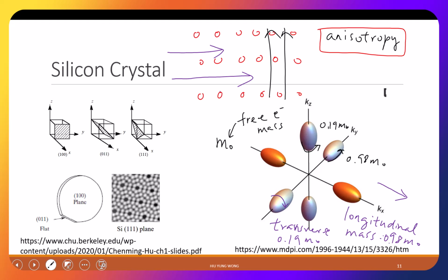Any questions? Yeah. Curious, is there some attraction or repulsion within the lattice? Yeah, it is like diffraction. You're right. The electron interacts with the lattice. But again, you solve the Schrodinger equation, come up with everything, and then effectively you try to find the so-called group velocity of the electron. And then you find out that it depends on the curvature of the EK diagram. But yes, the fundamental thing is that because of this periodic structure, you get diffraction and refraction, and that's why you can have this electron mass.